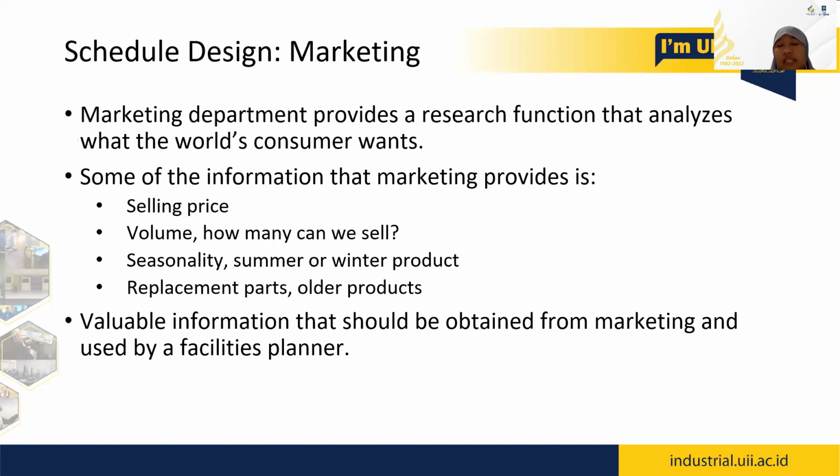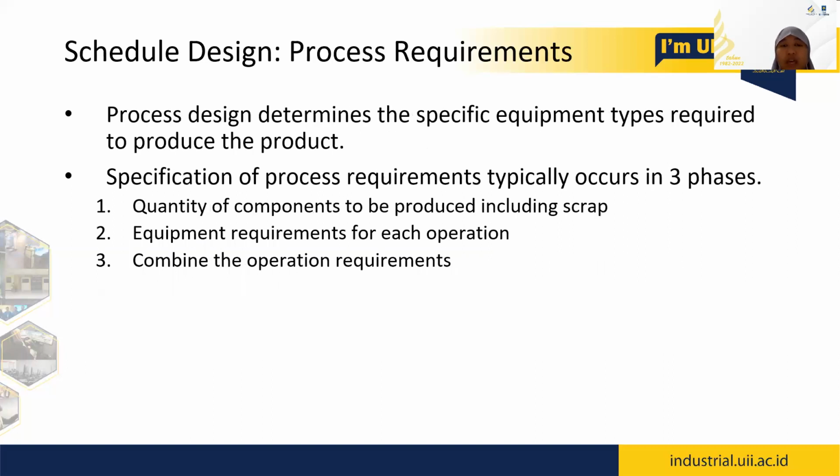Okay, so actually last week I already explained how each of the processes required will also need to consider the so-called defect or scrap when we are calculating the number of products we need to make, let's say, each year or daily. Okay, so once we understand each machine's scrap data, we basically can try to find exactly how much we need to produce.